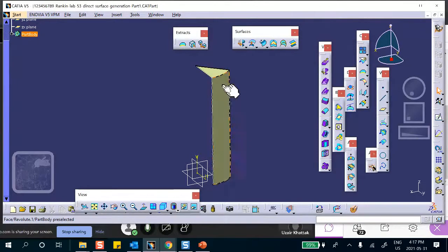So I don't need to join this. If in doubt, join it, okay? I don't need to join it for the same reason that when I extruded something, I did not have to join. In the second approach, where I create a solid object here, and by the way I'm going to shaft and then extract the faces, I will have to join these because these guys will not be talking to each other. Not here, though. This is fine.